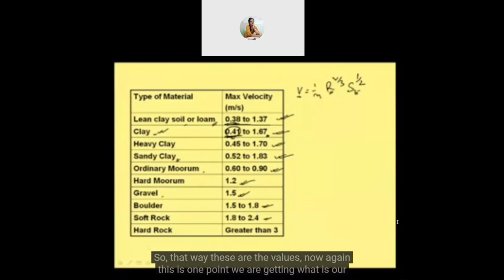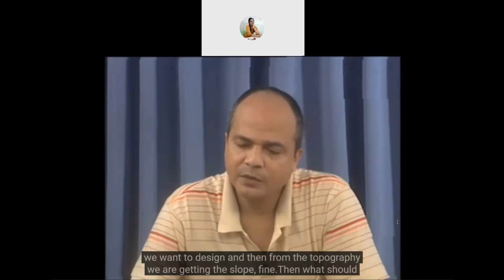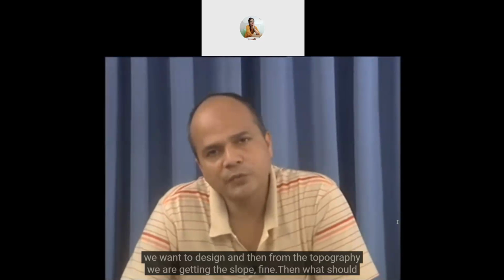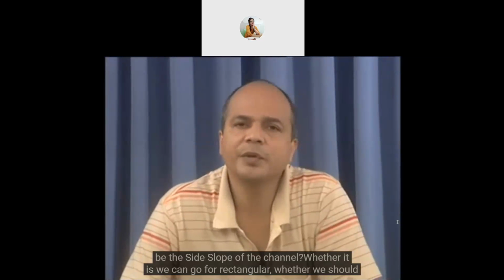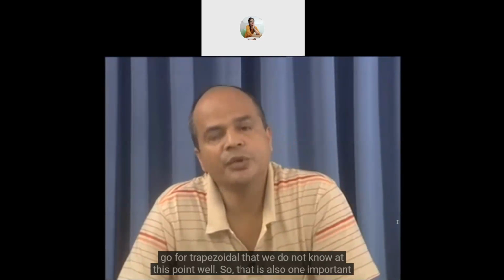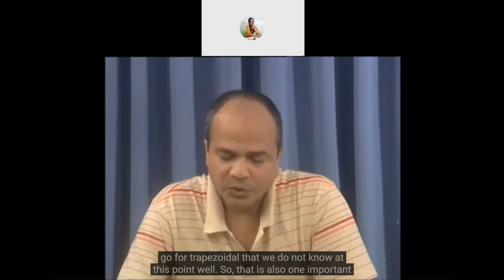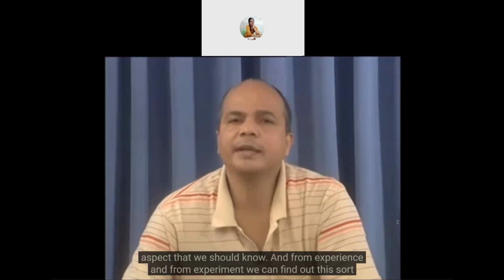Now, this is one point: we are getting our maximum velocity. Then before designing, we should know one more aspect. Say we want to design a channel, and from the topography we are getting the slope, fine. Then what should be the side slope of the channel? Whether we can go for rectangular or should go for trapezoidal, we do not know at this point. So that is also an important aspect that we should know, and from experience and from experiment we can find out this sort of value.